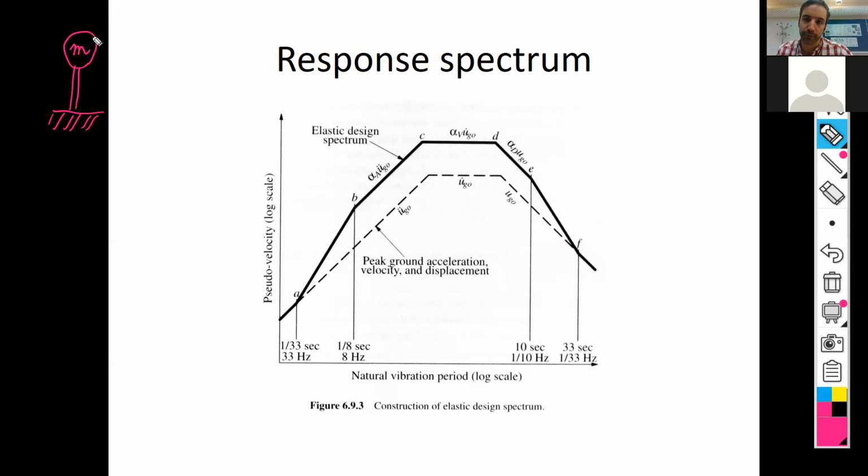It's like a 1 degree of freedom and all the mass is concentrated in one point. Structure in reality is not going to be like that. The structure is going to have a modal response of different shapes. For example, if we're talking about a bridge, it will bend like this. Or a building or whatever. So it is an oversimplification what I'm doing.